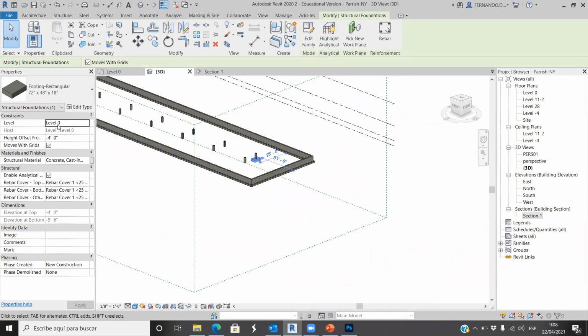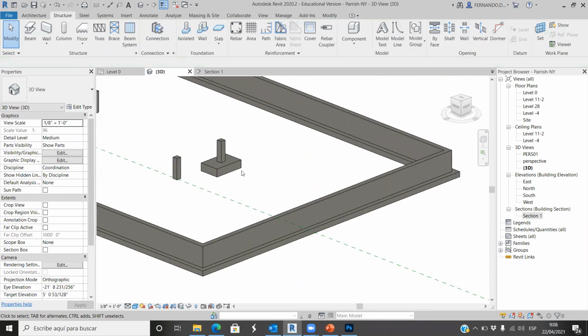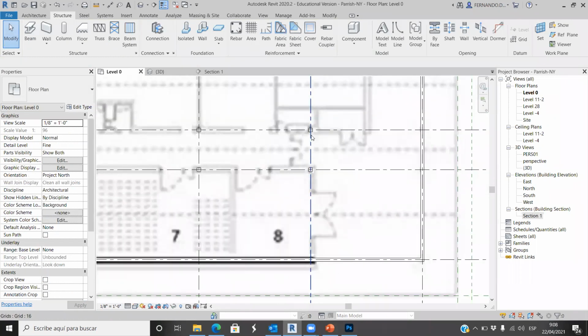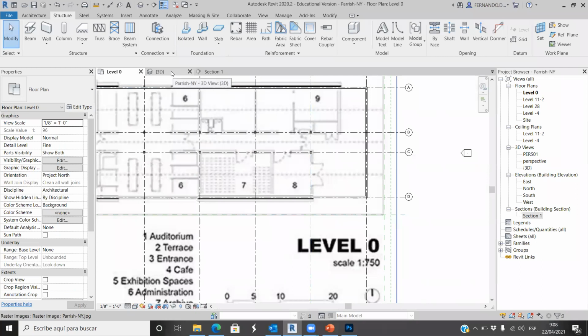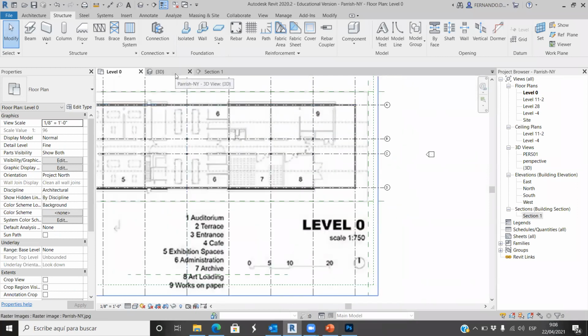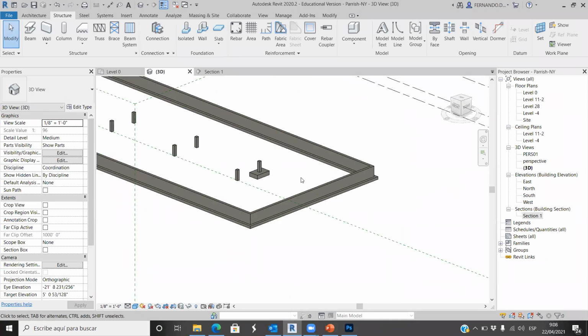Okay. Technically, it's on level 0 with an offset of -4. I would feel better if we type the level -4 without an offset. Yeah, I think that would be better. And now we can, we don't see this here. What about the 3D view?